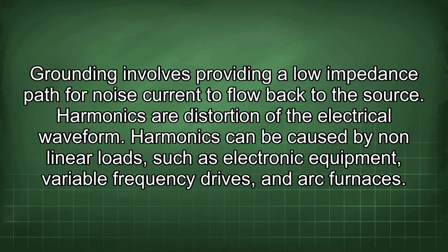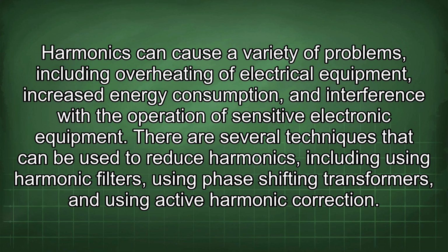Harmonics, a distortion of the electrical waveform. Harmonics can be caused by nonlinear loads such as electronic equipment, variable frequency drives, and arc furnaces. Harmonics can cause a variety of problems, including overheating of electrical equipment, increased energy consumption, and interference with the operation of sensitive electronic equipment. There are several techniques that can be used to reduce harmonics, including using harmonic filters, using phase-shifting transformers, and using active harmonic correction.